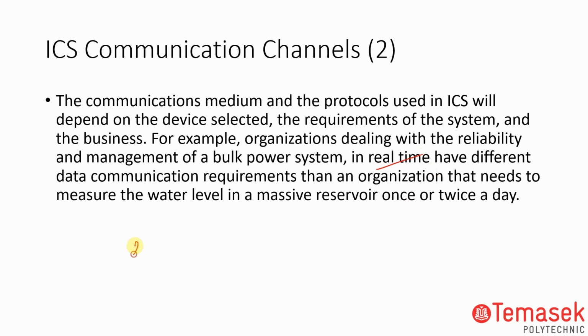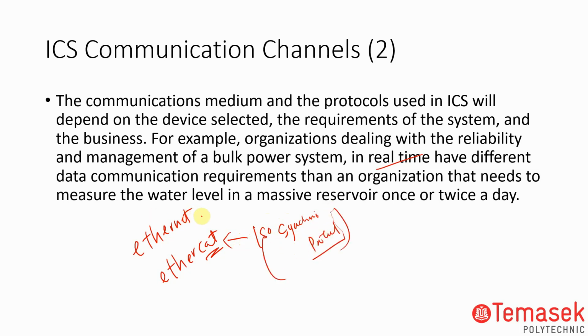That's why there is a thing called EtherCAT, but this is proprietary lah. Kind of proprietary at the end of the day. Okay, this one will give you a lot higher speed, because this and this are not entirely compatible with one another. EtherCAT is something like a cellular network. In terms of networking, we call it an isochronous protocol, whereas this is just an asynchronous protocol.